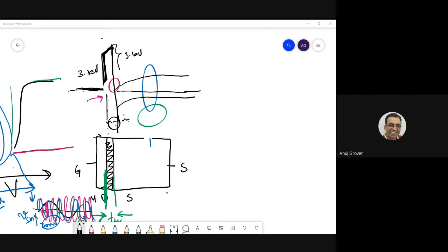The only definition of the inversion layer I gave was that when the band bending at the surface happens so much that you are only phi away from the conduction band instead of the valence band, you become as n-type as your p-type. That is when the region near the oxide interface has inverted. Sir, in this case, that inverted region will have some depth.